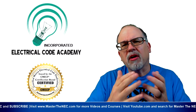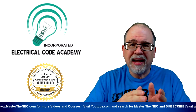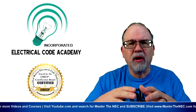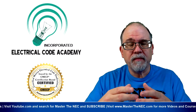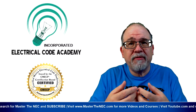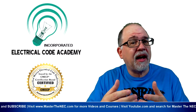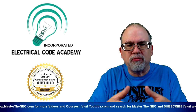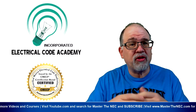Now, before we even do that, let's talk about transformers. What types of transformers are out there? Well, you have oil-filled transformers, and then you have what's called a dry type transformer. Oil-filled literally has some type of oil or coolant material that encapsulates the windings inside of the transformer, and that draws heat away from the core and the windings, which makes that transformer very efficient. Today's transformers usually have a non-toxic type of oil inside of it that helps facilitate that cooling effect. It radiates and dissipates the heat. It keeps it very efficient, and it helps it last a long time.